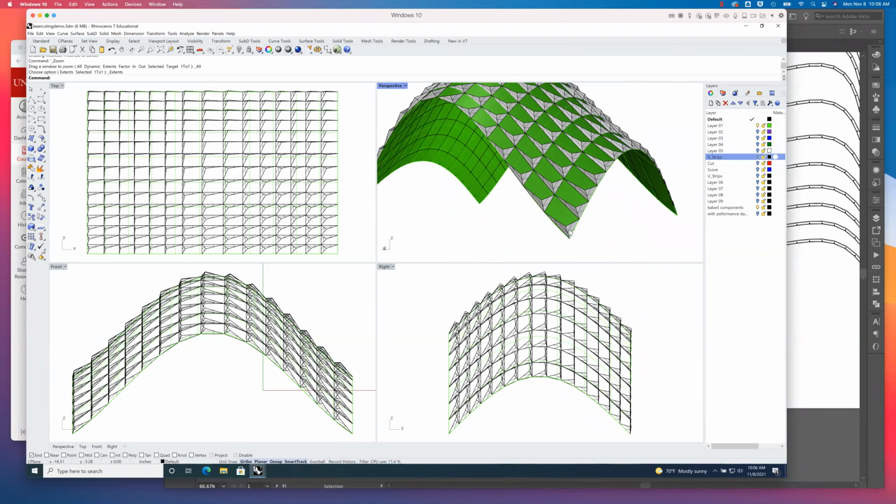Maybe they're south facing, and some of these might be north facing, right? Some of these cells, and so what we might want to do if we're actually trying to shade is to begin to understand which of these components, which of these cells actually get a lot more direct light, and then actually close up, make these cells a lot more opaque, right? In other words, we could begin to alter the properties, the variables, or the parameters of each of these shading components in order to close some of these apertures up where we need to, and then open them up on the north side where we actually have shade already.